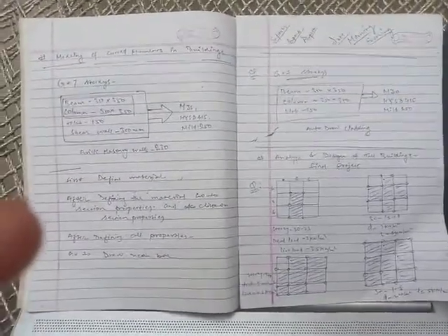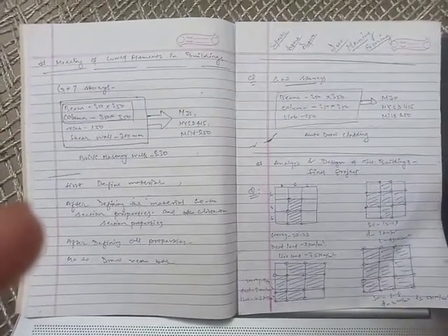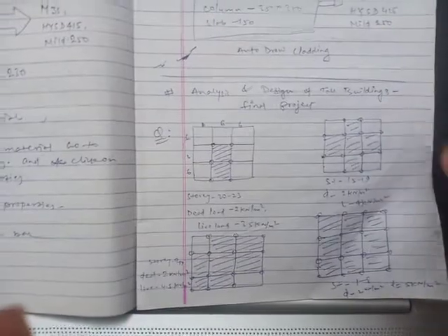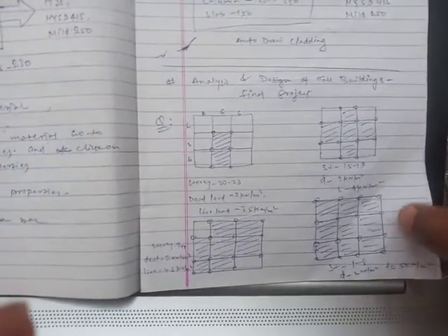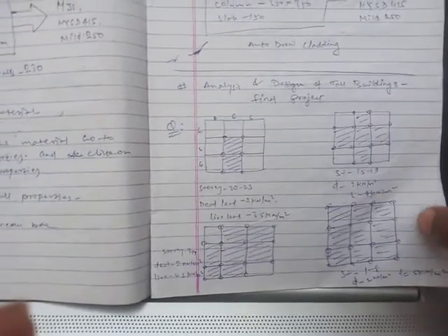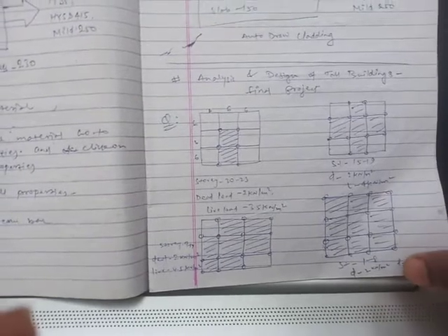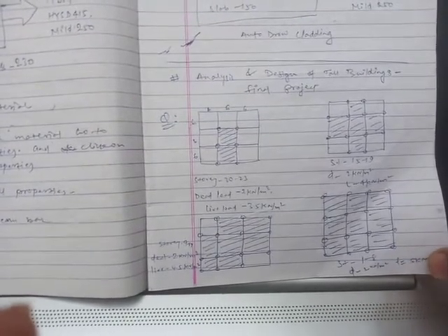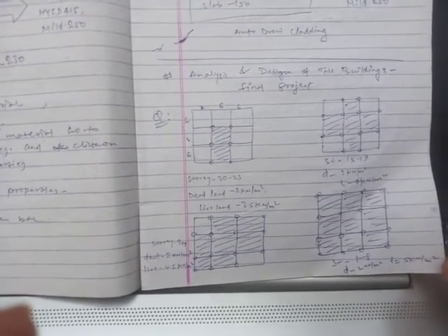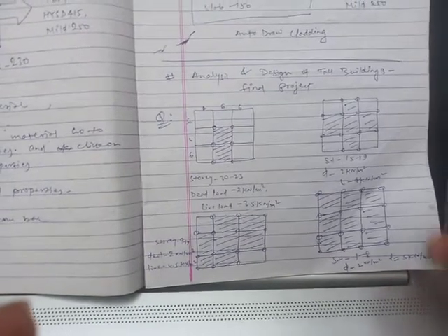I am here to make assignments of tall building design project. This is the tall building assignment project. Story 1 to 8, this kind of similar stories. Dead load 2 kilonewton per meter square or live load 5 kilonewton per meter square is applicable.